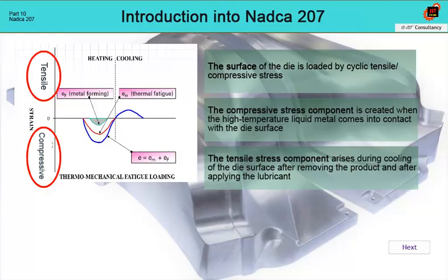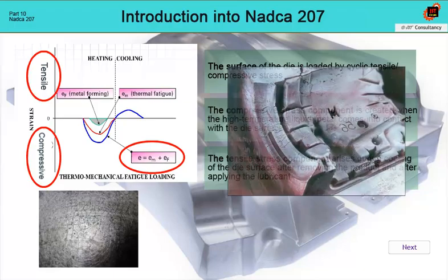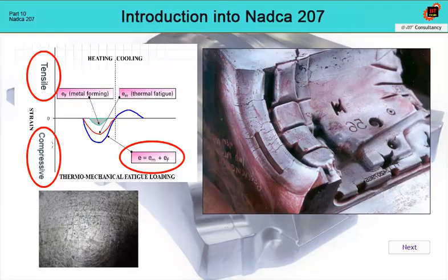During each cycle, a certain elastic stress is induced in the surface of the material until the plasticity of the material is exhausted. This accumulation of stresses leads to the formation of cracks from thermal fatigue. The question is how to measure the properties of the mold material and how to evaluate them from the point of view of increased resistance to cracking.